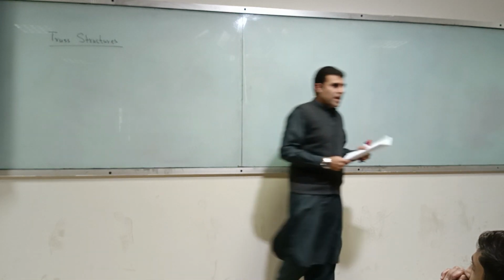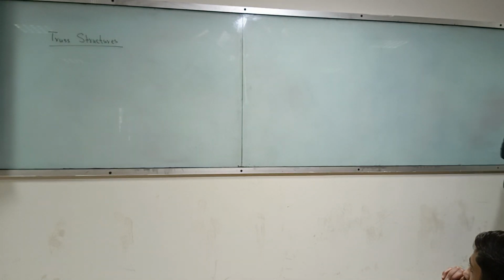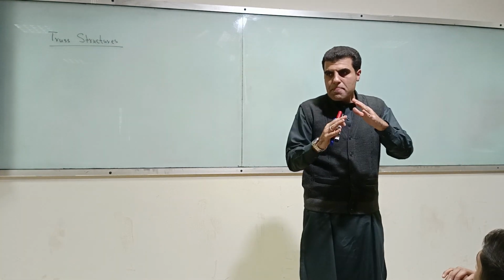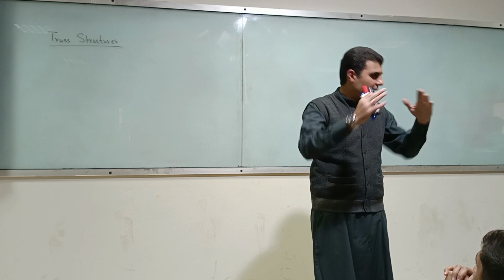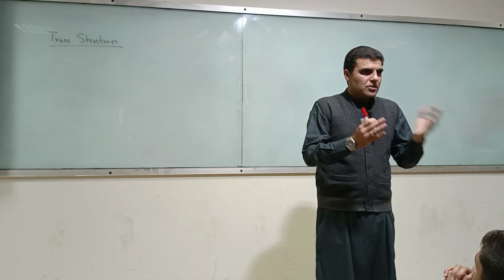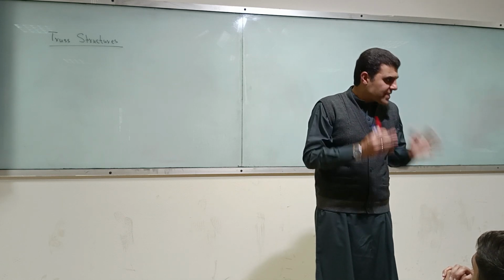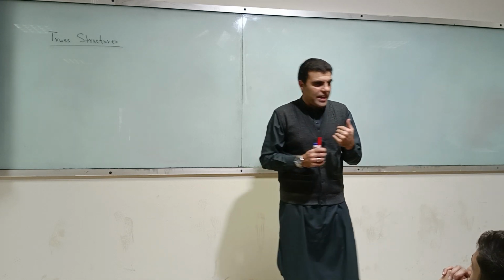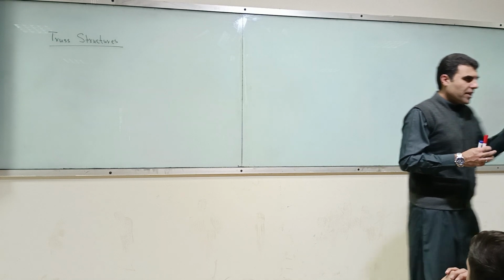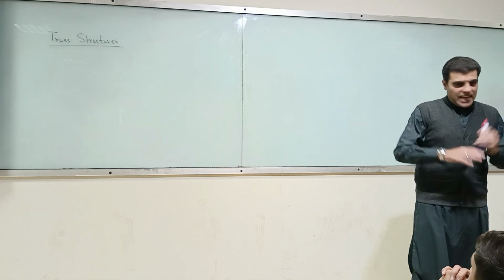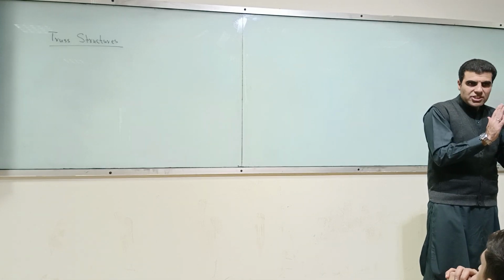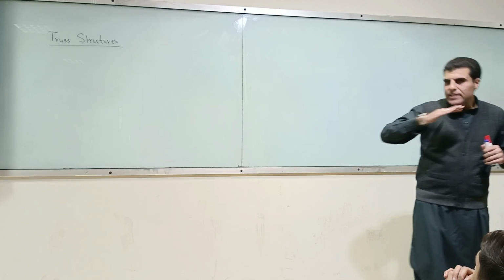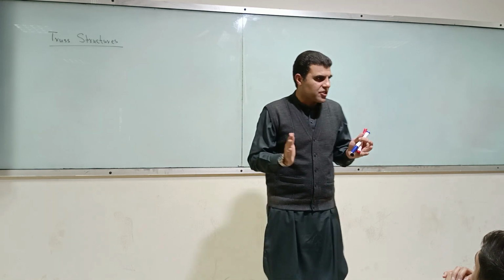In trusses, what we do is we provide members and we arrange them in such a way that they take the load axially. Only the axial load is absorbed by the trusses. These members are arranged through triangulation. So you provide triangles. A triangle is a stable structure.